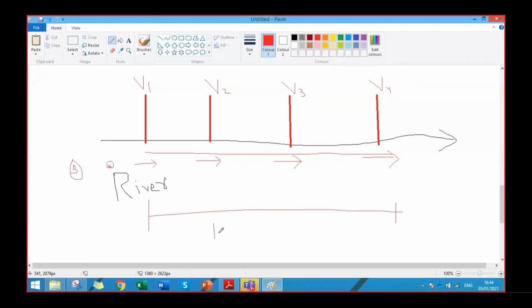So I have the variation of the property velocity for particle A in 10 seconds, let's say at 2.5 second instances for each. I'm seeing how the velocity of particle A is changing with every passing 2.5 seconds. Then there is another particle B behind particle A. It will also pass through these locations, and I will have the same readings for it. So I will have flow behavior at different locations with time as well. This is the Euler description. Is it clear?